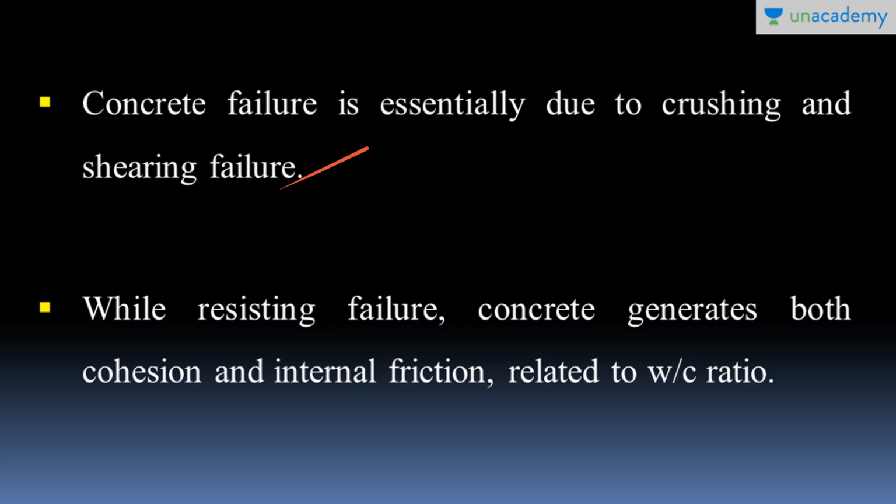Also, concrete must resist the failure. While resisting the failure, concrete generates both cohesion and internal friction. Both this cohesion and internal friction are directly related to the water cement ratio. That's why it is said that the water-cement ratio plays a very vital role in the strength of the concrete.